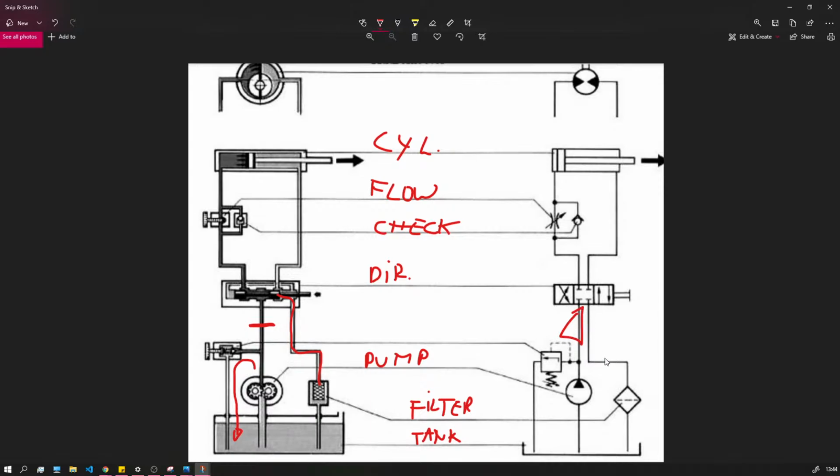And we can use return lines here, and we can use them in parallel systems connected to the tank. So there may be another pump on the tank which basically has the purpose of filtering the oil. So it's not using the driving oil through a filter, but a separate pump and a filter there. It's also driving the oil through a cooler, an additional cooler.